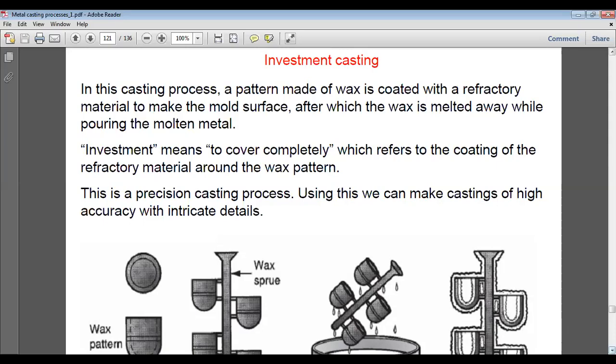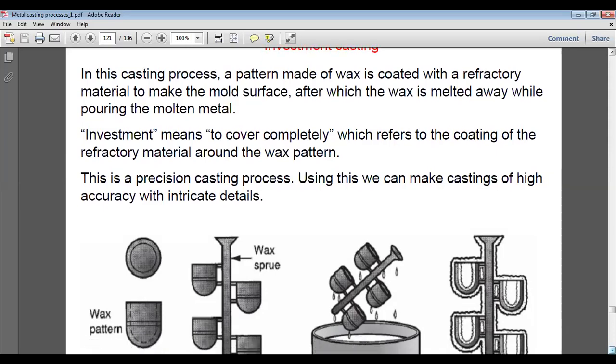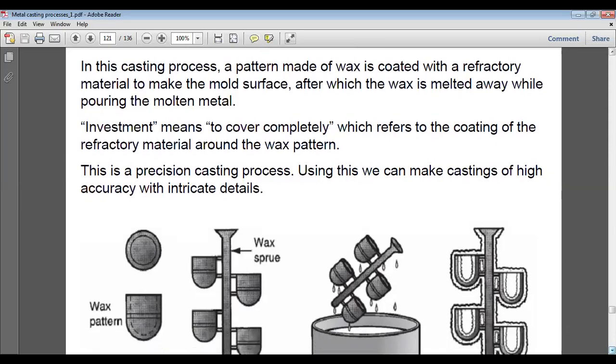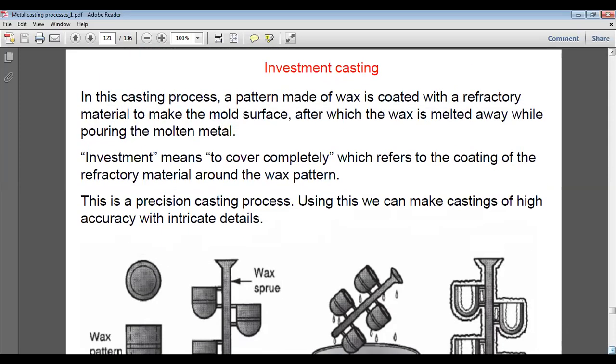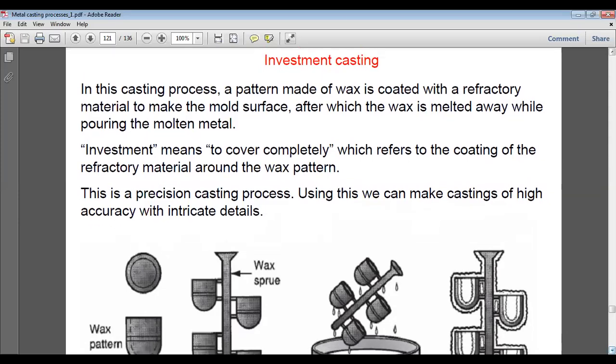We give a drain, a cavity, a capillary by which this molten wax comes out. So this is also a type of casting in which the pattern is not recovered and is lost. In the last lost foam process, we saw the pattern is converted into foams or fumes, and that is ejected by the system. But in this case, the pattern is converted into liquid, and this liquid is taken out.